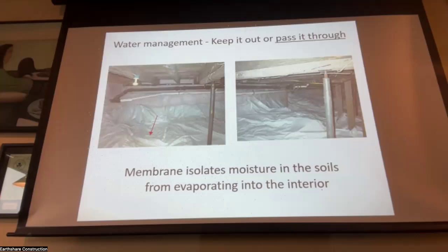So if you use a rain screen and do all of that, then yeah, you're likely to be pulling it out. Right, so we always put the fog machine inside the crawl space, pressurized it, went around the outside and found out where the leaks were, and then air sealed it from that perspective. But number one, if you do a depressurization test with fog outside and it gets into the crawl space, you can't clear it. So you can't seal the joint and then do another fog test because the crawl space is full of fog. Don't do it that way.